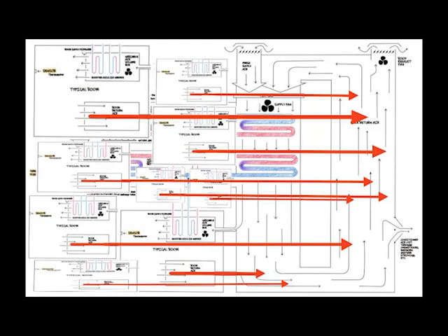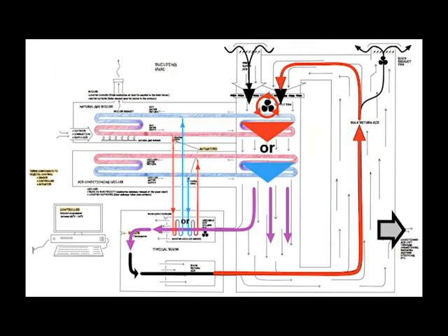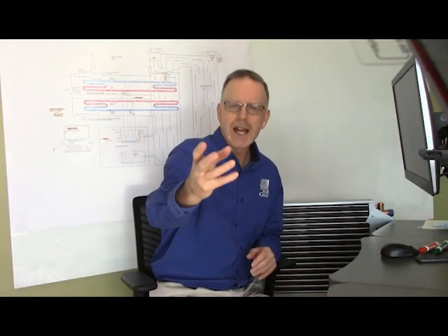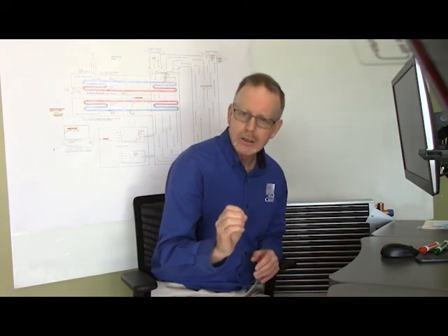Return air is pulled from many rooms and building spaces. This return air is in need of freshening, filtering, and usually needs conditioning, heating or cooling as well. After freshening, filtering, and conditioning, we now call it supply air, which is distributed to rooms and building spaces. Once used, it becomes return air again and is sent back for freshening, filtering, conditioning, and so on and on. Now that you have the main ideas, let's take a closer look.